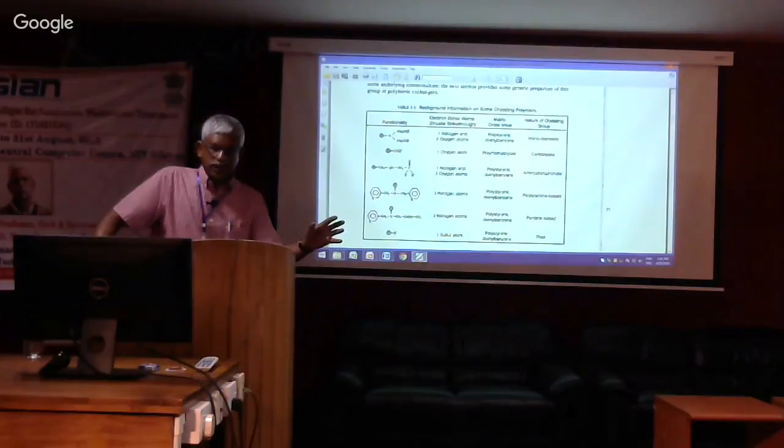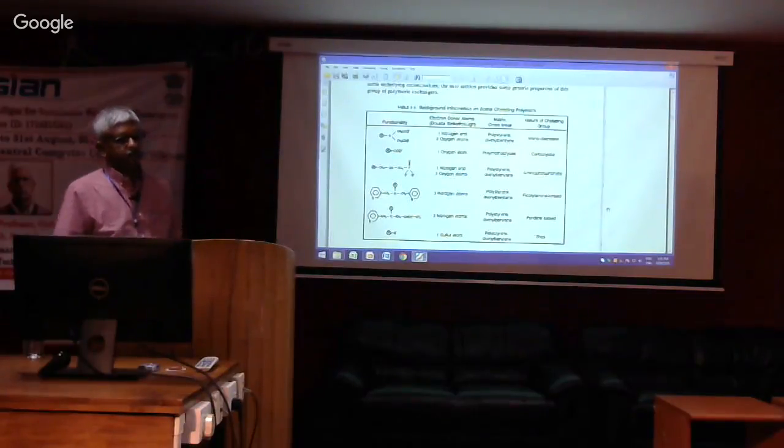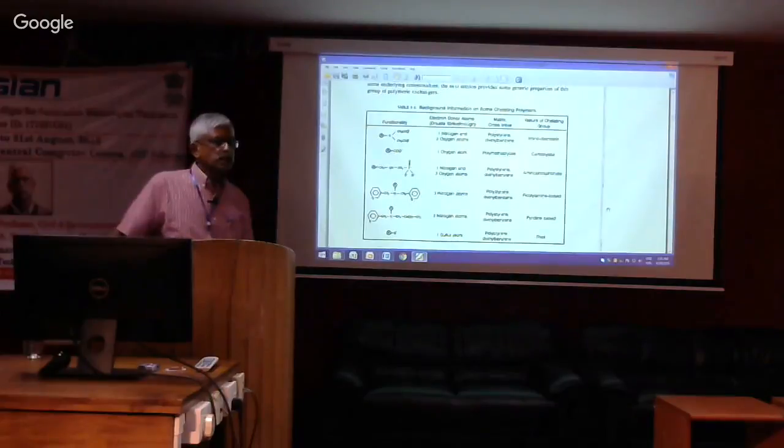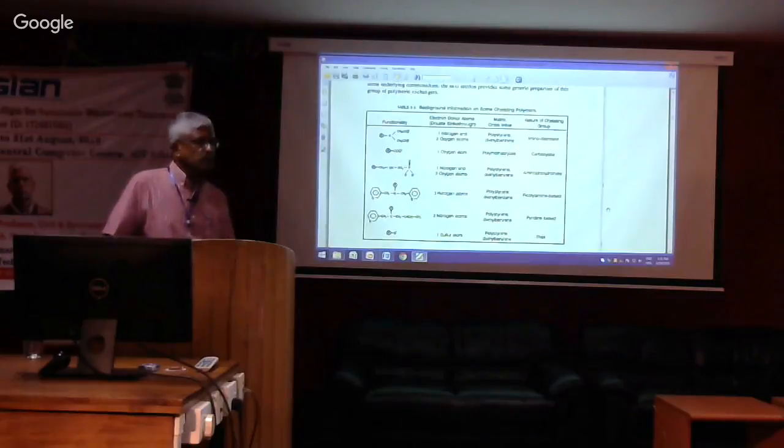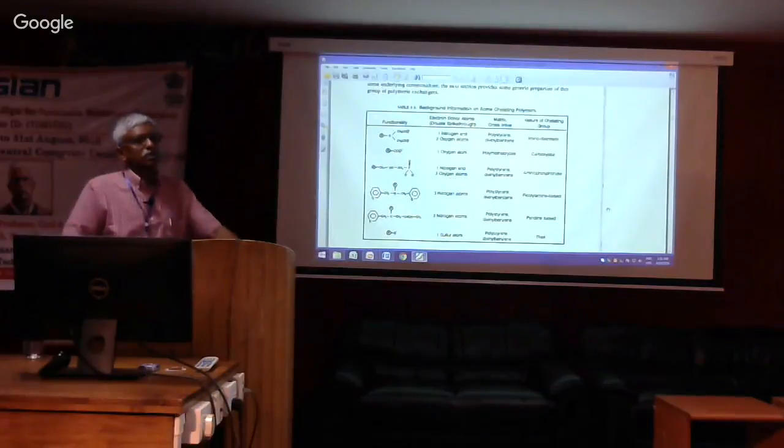But what you can also do, and what people have done, is you can also use a weak acid resin, and in that case there are certain advantages in the sense that regeneration is so much better because you just have to reduce the pH, and you bring the resin back in H plus form. But then you have to do another cycle where you have to go back in and replace the hydrogen with sodium. So it's a two-step regeneration process, whereas a strong acid is just a one-step.